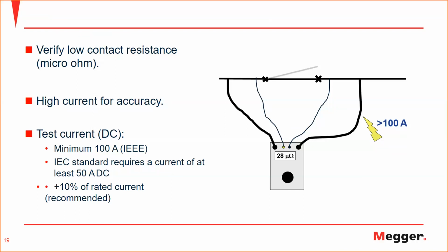And the reason for that is that, if you remember in one of the slides that I have explained, especially in SF6 circuit breaker, we have two types of contacts, a main contact and an arcing contact. In the main contact, I can measure it easily or verify that it is working correctly very easily with just normal contact and static resistance. But the arcing contact will be in parallel with this main contact. So if there's any problem to that arcing contact, I will not be able to see it.